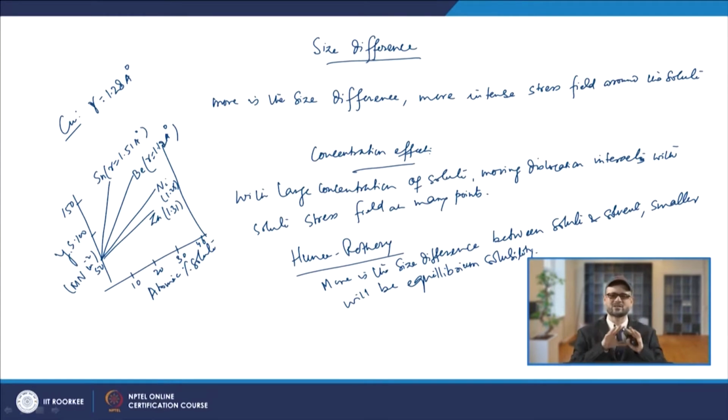Given the way the lattice structure of iron is, you have two types of voids, tetrahedral and octahedral. As you know, there is larger solubility of carbon when you increase the temperature, and then when you are decreasing from there.